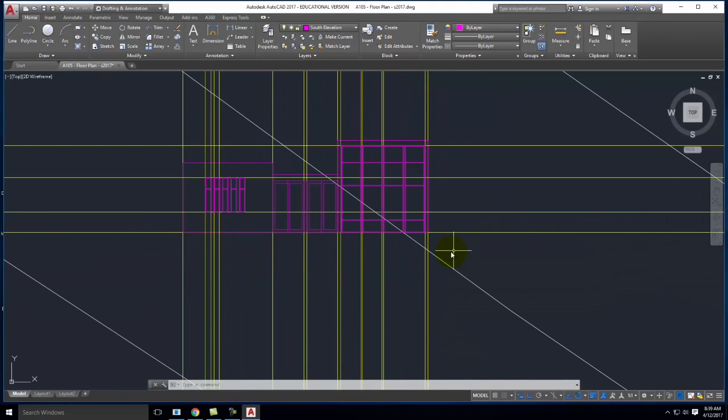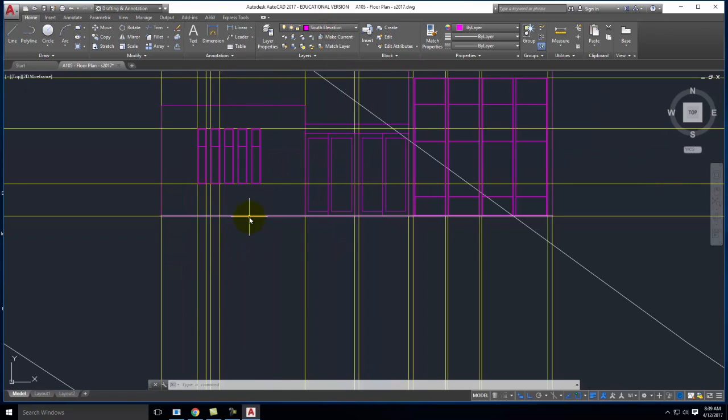So I've done a lot to establish this elevation, but I haven't yet dealt with what happens below the building. Okay, remember, there's always a little bit below the floor of the building. And I think it would be safe to say minimum 18 inches or so. Okay, 1'6". So in the most simple terms, all I would need to do is, remember I'm on the south elevation here, all I would need to do is offset this down by 18 inches.